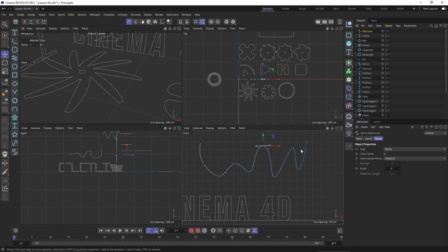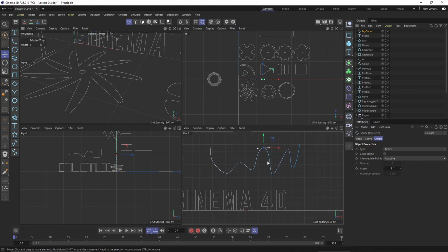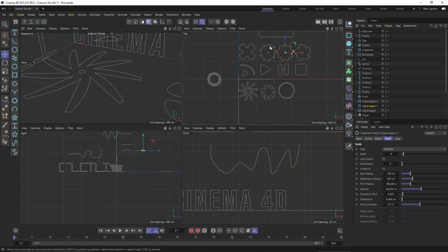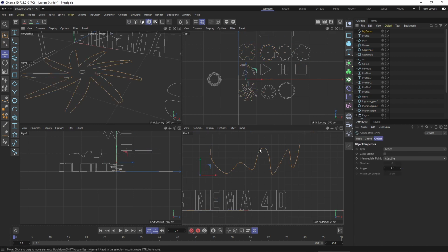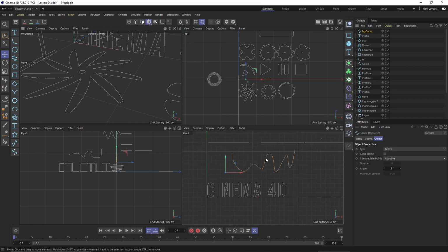Now we're gonna stop here in this video, but we will continue to talk about drawing and 2D drawing and 2D editing later on. But what I want to show you here is that we are working now in this mode, which is the points mode. Now, when you want to get back to the standard mode, just click here in the model, and then you can select and manipulate the models and not the single points. But you can always go back to points, to edges, to polygons when you do 3D modeling, and to model when you want to work with the whole object and not with the sub-object.